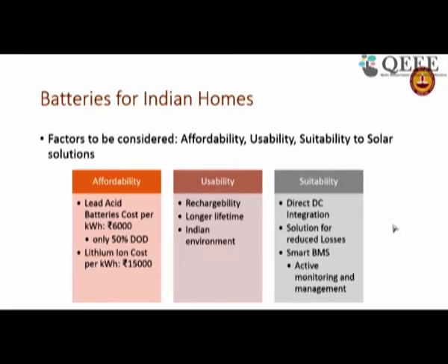Lithium ion, with a higher number of cycles, around 15,000 rupees, but 15,000 rupees is not available as easily, it's now closer to 22,000 rupees. But this can do 90% depth of discharge, so if you really look at it, it's 12,000 rupees. But the initial sum cost is small, so sometimes lead acid is still considered the favorite. Lithium is coming up very quickly, cost is going down, and in years to come maybe lithium will take over.